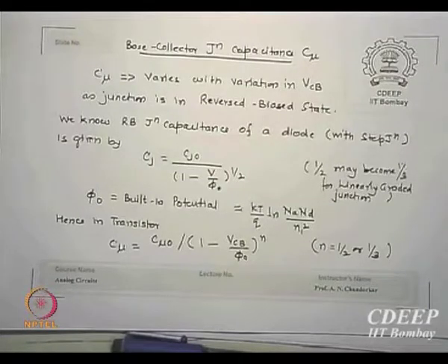There is a built-in voltage sitting there. Is that correct? So the diode, even at zero bias, is equivalent of a capacitor, because there is a depletion layer intrinsically present. That value, epsilon A by depletion layer width, is the capacitance. Epsilon A by D is capacitance.